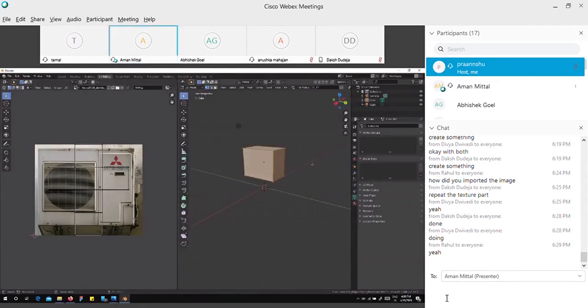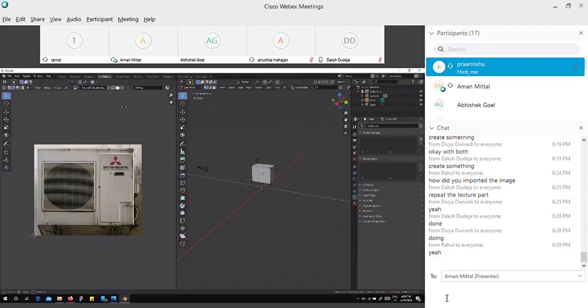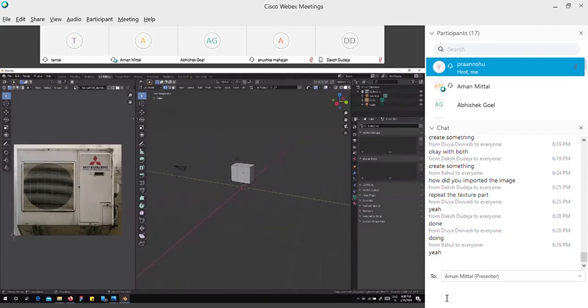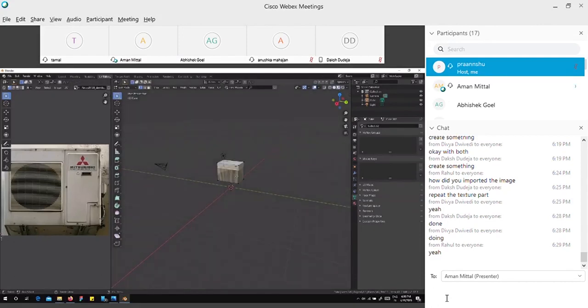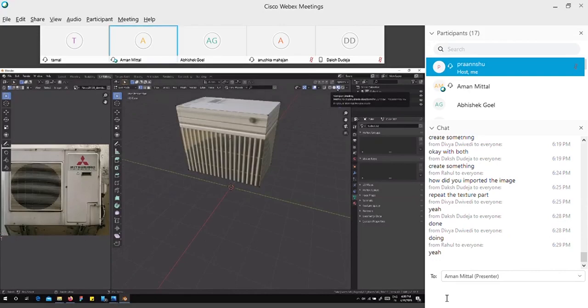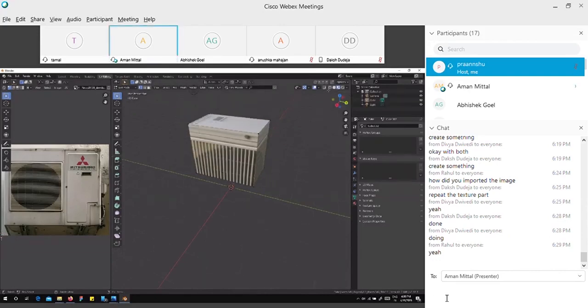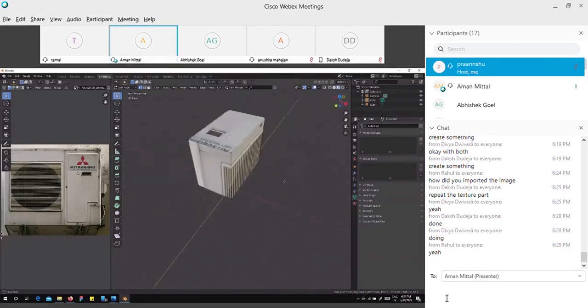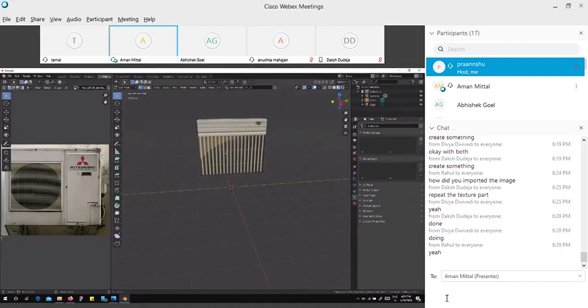I will just put this viewport shading option on. This is the third one from the first. Now what we will do is select each face. Now in edit mode, as Tamal told you, we can select a vertex, edge, or face. So by selecting the face here,